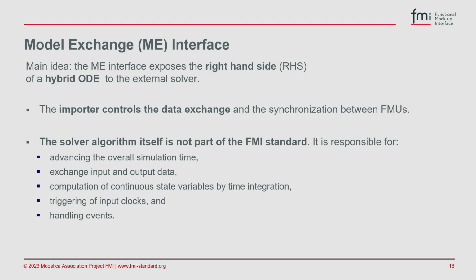For model exchange, I think we explained these things already. There the idea is you have more or less the equations and expose them to the solver of the importing tool. And also here, it's not defined by the FMI standard which solver the importing tool uses. It's up to the users to select a suitable one.